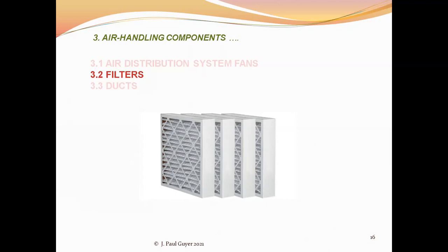And the filters, the more robust they are at doing their job of filtering out particulates and bacteria and things like that, typically they also impose a greater load on the electric energy requirements, because it takes more electrical energy to run the fan to push the air through the filters.